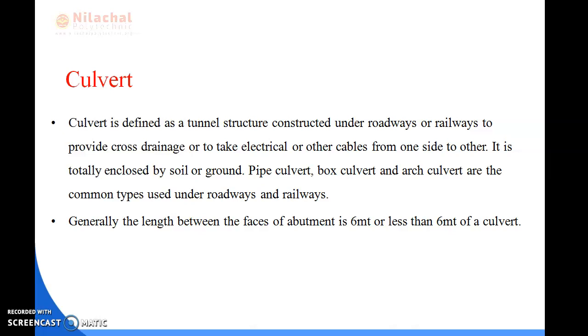Culverts come in many sizes and shapes, including round, elliptical, flat, open bottomed, pear shaped, and box-like. Many shapes are there. The culvert type and shape selection is based on a number of factors, including requirements of hydraulic performance, limitation on upstream water surface elevation, and roadway embankment height. Here is the definition of culvert.